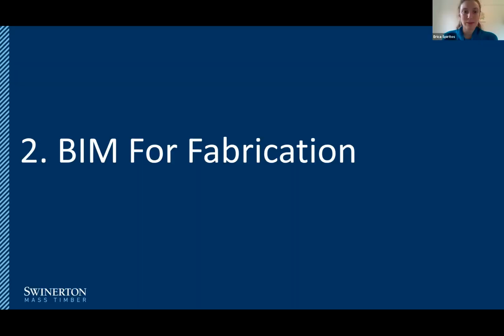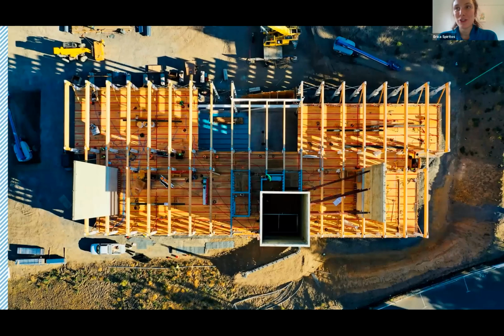So can these be used for exposed conditions? Mark asks. We can definitely utilize glulam in an exposed and exterior application. We'd want to be thoughtful about coatings or wood species selection to reduce weathering over time and to protect that wood from degradation from the elements. So definitely doable, and there are a number of ways to protect the timber.